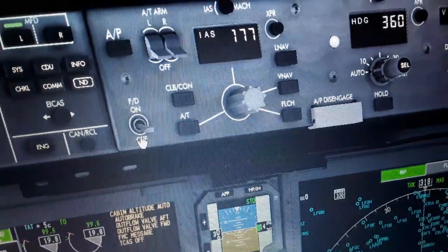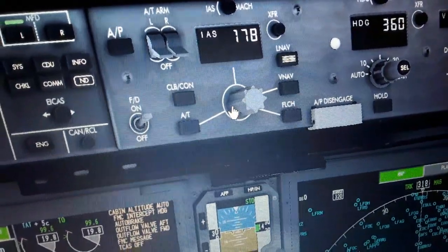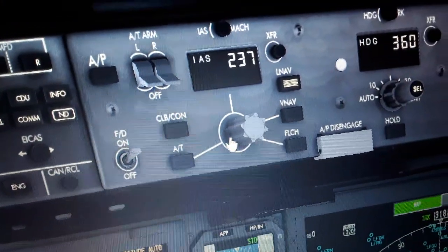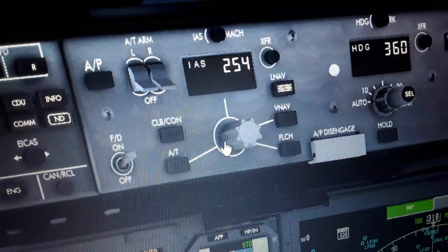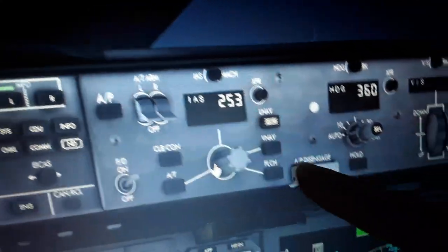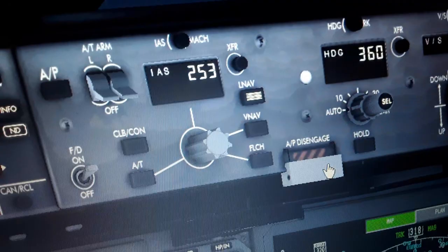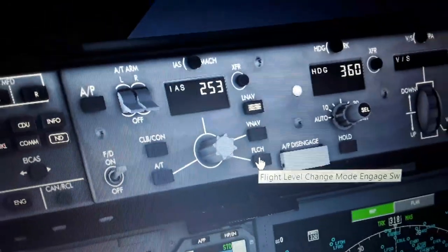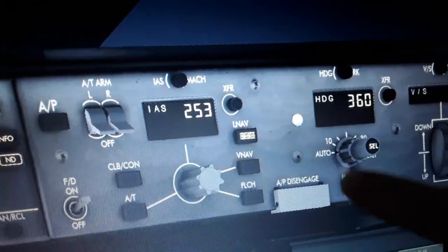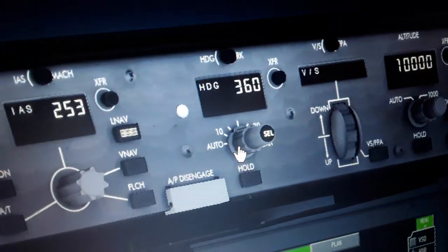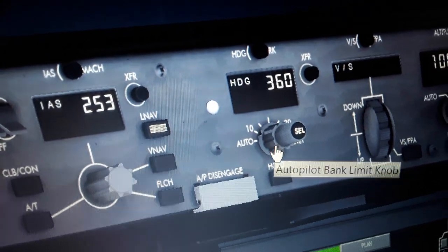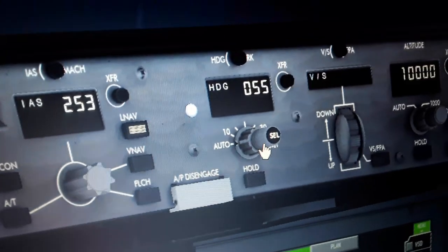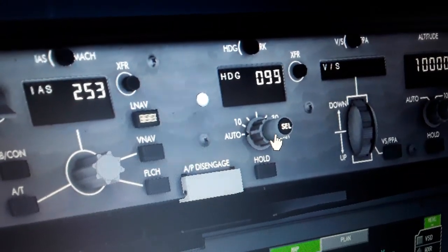We cannot rearm with the autopilot. So we need the flight director. This switch on. Set the airspeed for takeoff. After takeoff. So this flight director, autopilot engage and disengage. Flight level change, VNAV, flight level change, auto throttle, climb continues. The heading guidance of the aircraft, bank angle limit in flight, has steep banks, and the hold for the heading. So we're gonna use magnetic North Pole heading, 136 degrees of the runway. We're gonna use for takeoff and for landing.